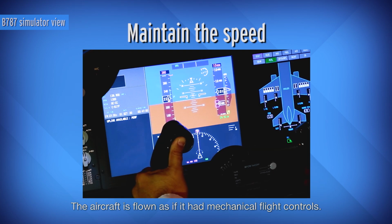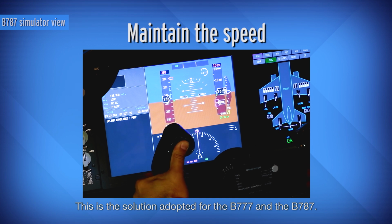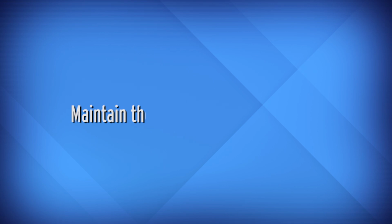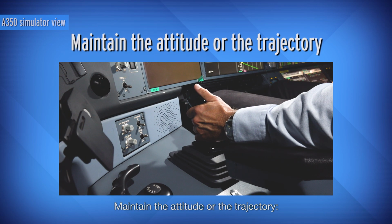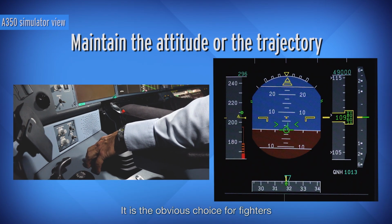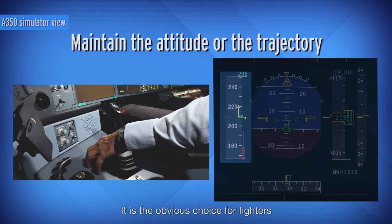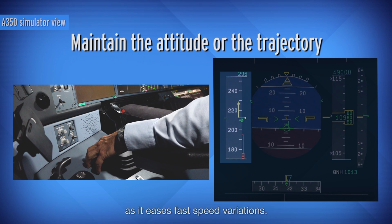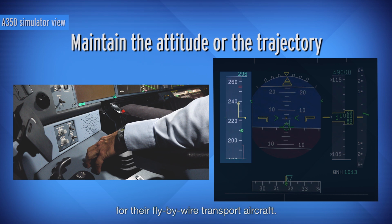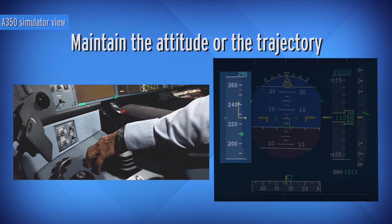The aircraft is flown as if it had mechanical flight controls. This is the solution adopted for the B777 and the B787. Maintain the attitude or the trajectory. With such a law, there is no need to trim when modifying the speed. It is the obvious choice for fighters as it eases fast speed variations. Airbus and Dassault Aviation also made this choice for their fly-by-wire transport aircraft.